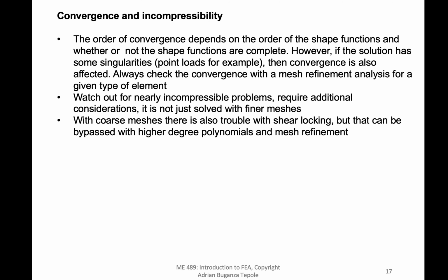Another type of problem that you might have is incompressibility. I want to bring this up because we have also talked about the idea of convergence. When you have a mesh for a model, you run the simulation, you get some values, then you refine the mesh, you get new values, and maybe they look very similar to your first simulation, but a little bit different.